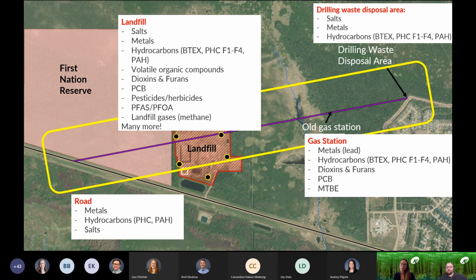And then is there criteria for the age, size, intensity in order to make an APEC? Understanding the APEC, it's more judgmental. It's just understanding your site history, what the potential contaminants are, and what the uses of it are. So it could be big or small. An APEC could be as small as a burned out car or a vehicle that has some soil staining underneath it, or a heating oil tank, to an entire industrial site.